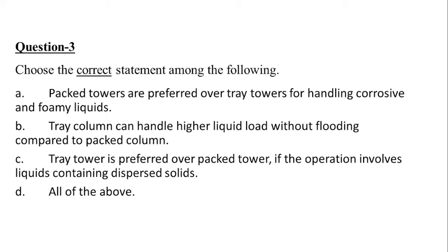So let's see the options. They are asking which one is correct. Packed towers are preferred over tray towers for handling corrosive and foamy liquids. So option A is partially correct, as packed towers are preferred for handling corrosive fluids, but they cannot handle foamy liquids. Foamy liquids are mainly handled using tray columns. So option A is incorrect. Option B, tray column can handle higher liquid load without flooding compared to packed column.